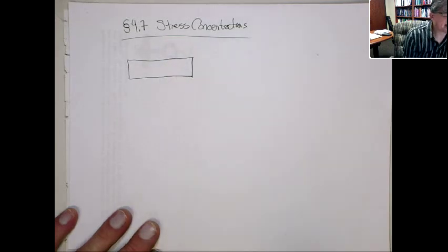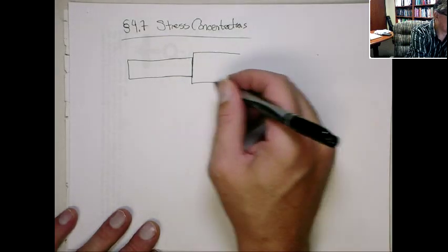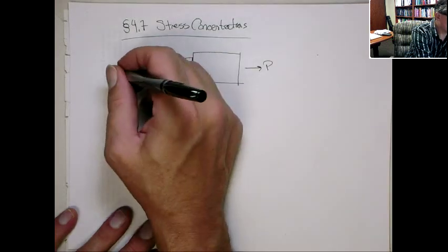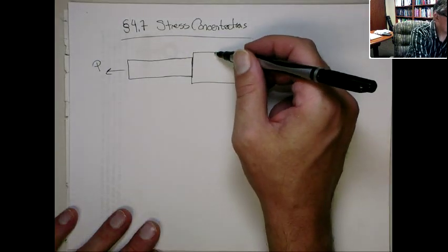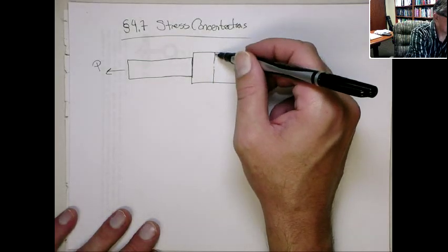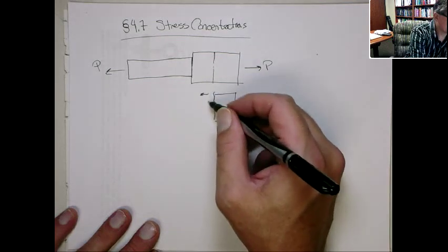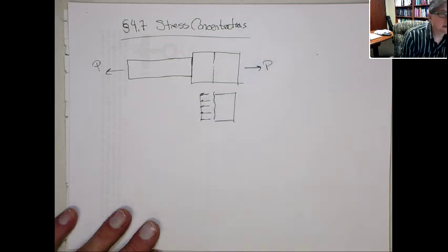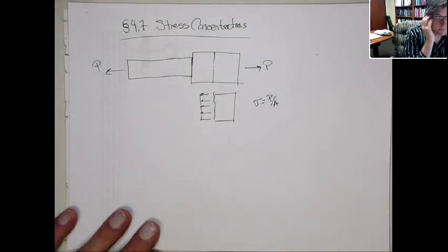this idealized axial loading case, lots of variants of it, maybe a stepped shaft or whatever, where the loading is assumed to apply in such a manner that the stress distribution over the faces is constant, right? So if you cut this, we're assuming that the actual traction over that face resulting from the normal stress is basically uniform. And so then we can get that stress is the force over the cross-sectional area, right?